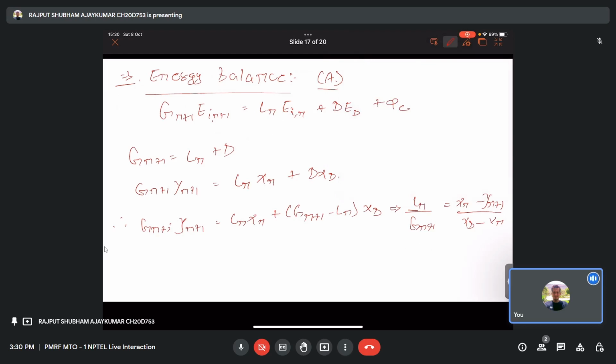It's better to see the equations. We assume that the reflux may be a subcooled liquid for the rectifying and the stripping side. For the rectifying section, we assume that the reflux is a liquid at its bubble point, and in general xD is the mole fraction of the more volatile component in the distillate. Similarly, you can draw out the material balance for the component and determine the energy balance for the stripping section also. But instead of going into deeper points again and again, it's better you go through the energy balances.